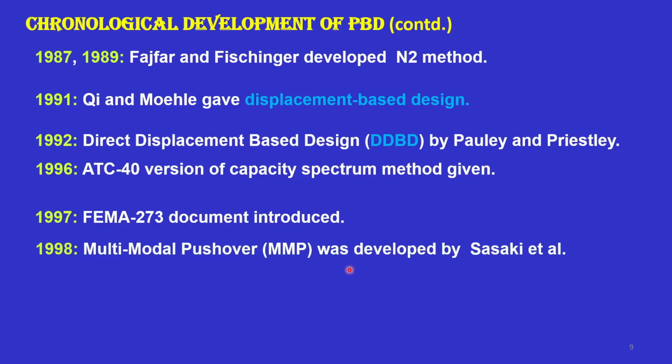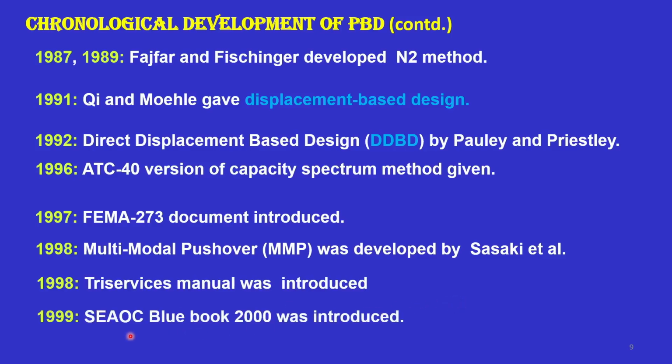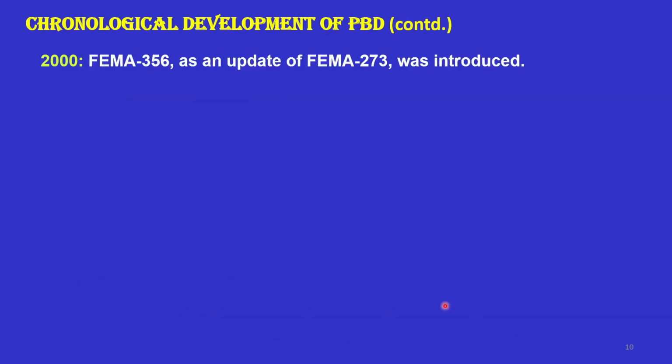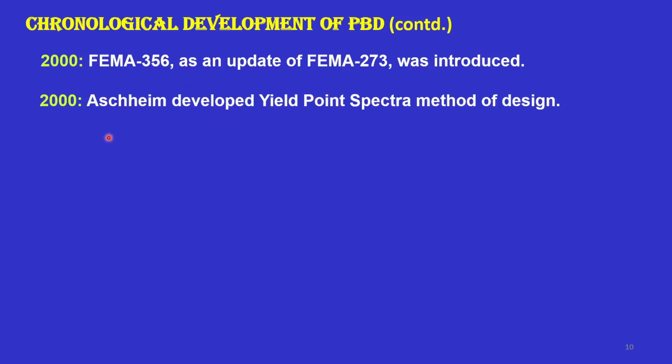1998, multimodal pushover analysis was given by Sasaki et al. 1998, tri-services manual was introduced on earthquake design. 1999, SEAOC, Structural Engineers Association of California Blue Book 2000 was introduced. 2000, FEMA 356 is very famous. 2000, again, Aschheim and Black developed yield point spectra.